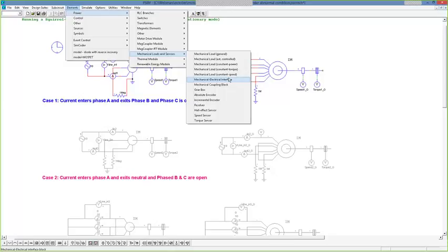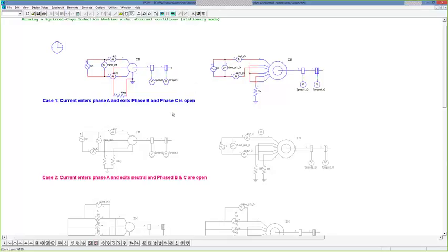For example, someone was describing to me a sensor they were trying to generate. It was sensing the torque, and it slowed the shaft down, but it didn't actually affect the torque flowing through the element. It sounded to me like the equivalent of a diode effect, so we just put two mechanical electrical interface blocks and a diode in the middle, and that did what they wanted. But let's look at these circuits now.